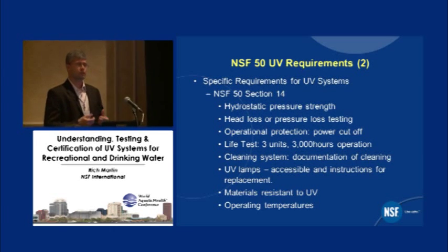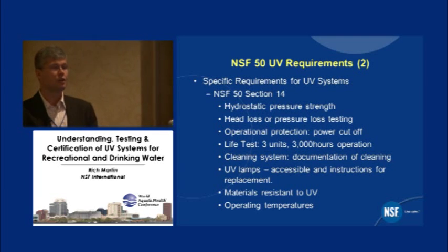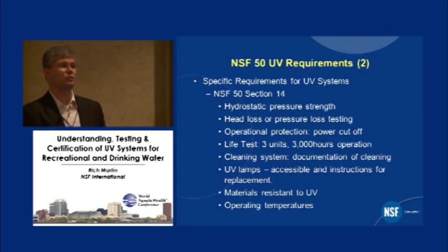Also doing the pressure loss testing. Anytime you have anything in the waterway, you want to know how much pumping losses there are so you can properly size the pumps and make sure you're not underdriving the system and getting insufficient circulation.